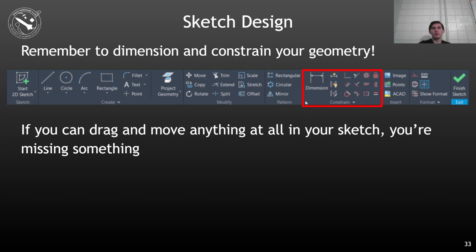Another thing, so this is where all of your constraints are going to be. This is what's going to basically lock your geometry in the right places. This is where you're going to get exact dimensions and measurements for things. So the dimension tool, very basic. It's literally you click a line, you type in a number, gives you the length, or it modifies the length for you. Or you pick 2 lines and you pick an angle. Any kind of number that you can put to a measurement, you use that dimension tool. It does everything automatically. It'll automatically identify what type of measurement you're trying to make.